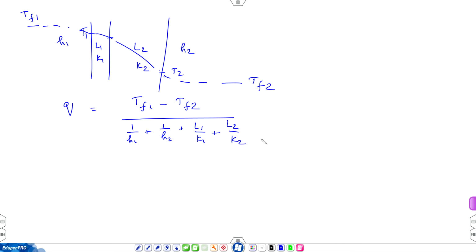Okay. So, thermal resistance is like a global analysis. This approach will not give you intermediate temperatures. For that you have to solve the governing equations. It is a global approach. It gives you the total heat transfer for the applied temperature difference. In case of an annular region, it will be log r2 over r1 divided by 2 pi k1. That is the resistance contribution of an annular region.